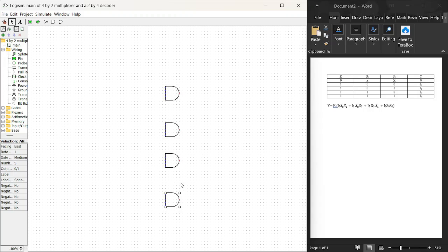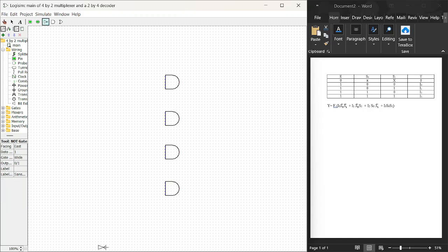And I have a negative, that's a 0 in it, so I'll have to introduce my NOT gate. Let me place my NOT gate somewhere here. I need two NOT gates, so here, and this is my OR gate. This will be used to link all the inputs which will pass through the AND gate, and it will be receiving 1, 2, 3, 4. So I change the number of inputs it should collect to 4.